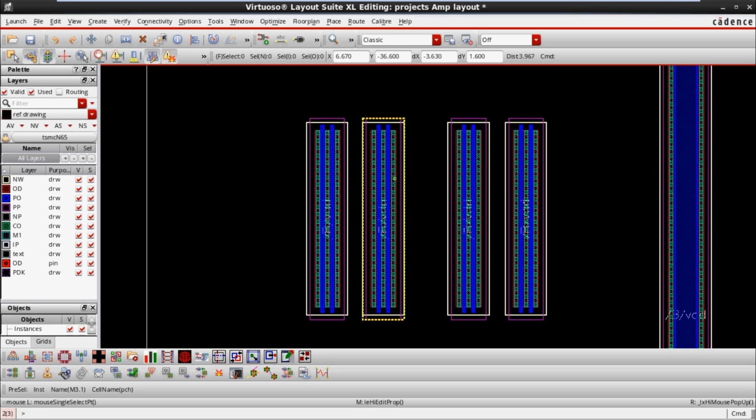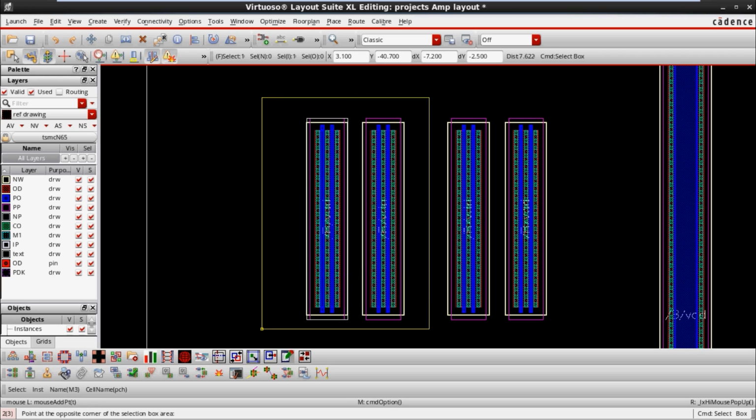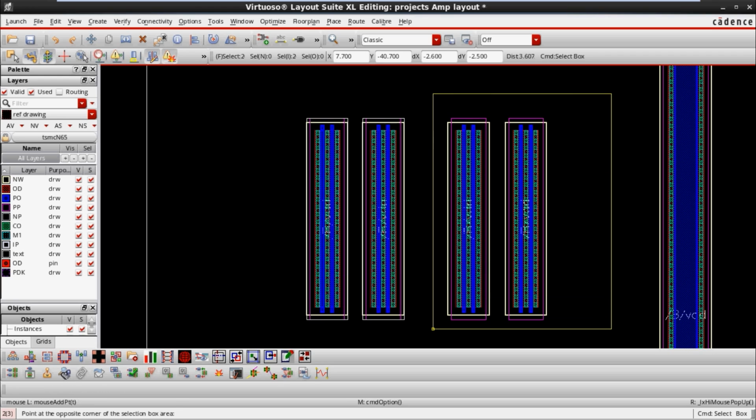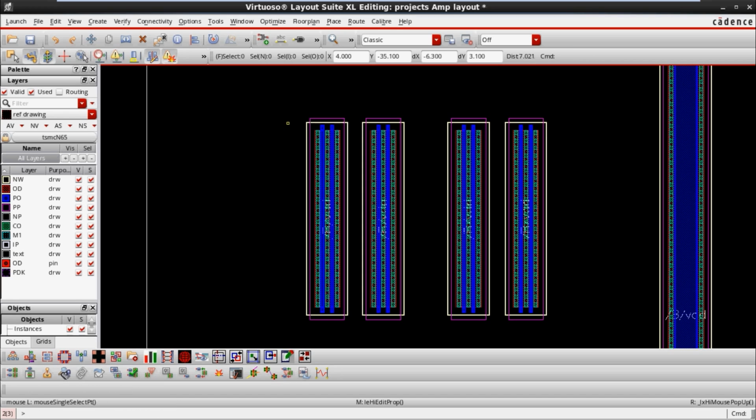So now this is a diode structure. These 2 devices are denoted as a diode, and these 2 devices are denoted as normal devices. Usually whenever any layout or schematic designer places the diode in between for matching, since it is a current mirror, we can go for a common centroid also, we can go for interdigitization also. It is not mandatory that a current mirror compulsorily should be done with interdigitization, or a differential pair should be done by common centroid; it is based on our requirements, based on our wish.